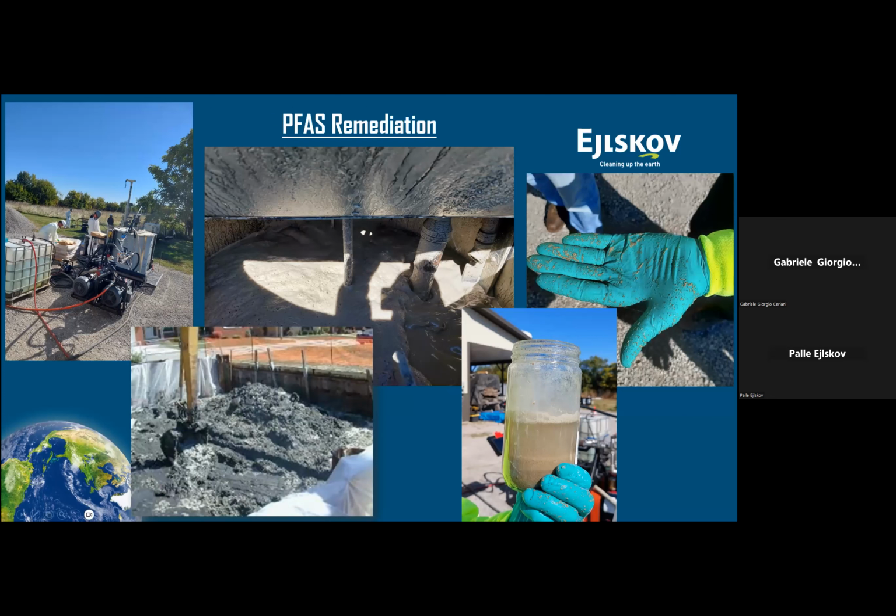So everything that we've discussed thus far has really been the activated carbon-based products, but really these injection systems and techniques can be used for other slurries as well. And activated carbon is not always the best option for in situ applications, due to the nature of PFAS and the likelihood that it's going to ultimately get discharged off of the activated carbon. And so we've got involved with Setco, based here in the US, who have developed a modified clay product that absorbs PFAS better and longer than activated carbon.